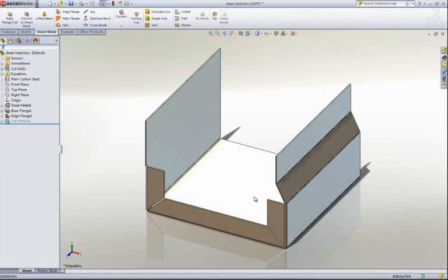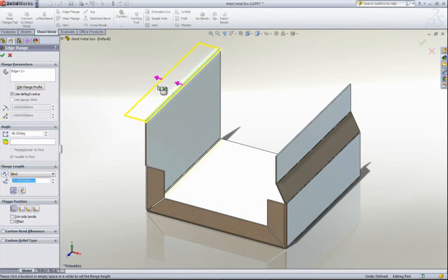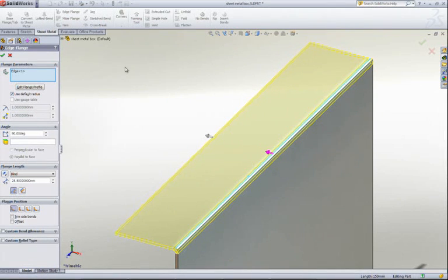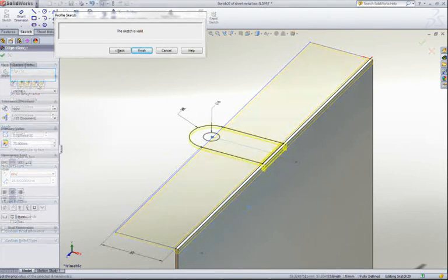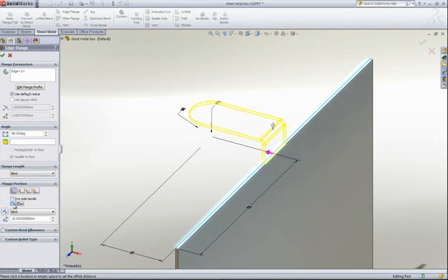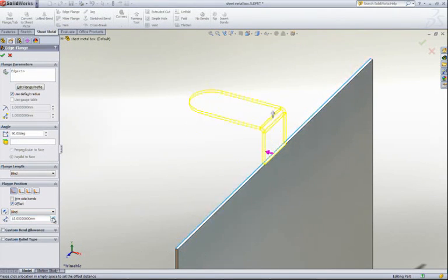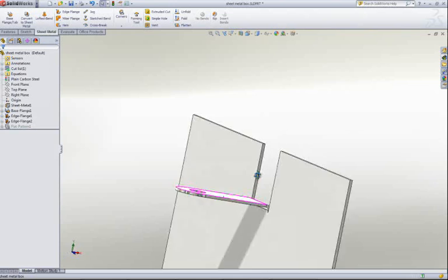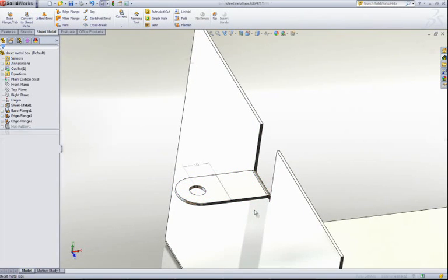Modifying the length of a flange is not enough. You need to have the flexibility to create custom flanges without having to add additional features to complete the task. For instance, SolidWorks lets you edit the shape of the entire profile and even add holes all in one go, and then modify it even further with an offset to add or remove material in the bend area. This saves a great deal of time and effort to get to the finished design fast.